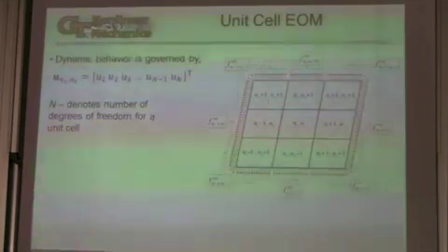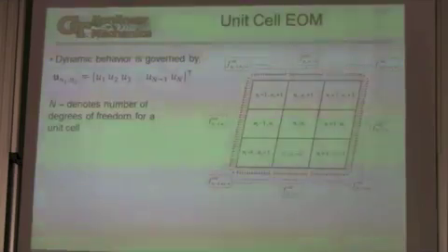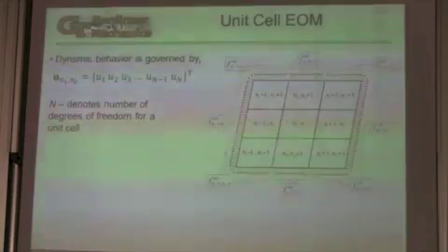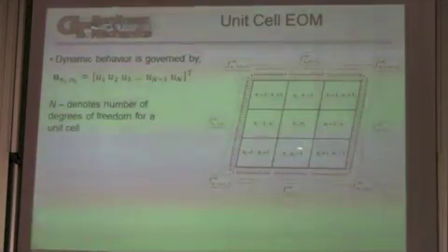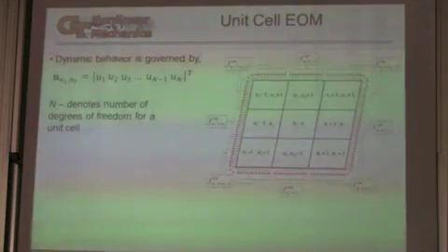Now, the promise with this periodicity is we can reduce everything down to a single unit cell. Let's say we're going to work with the center unit cell. And when we work with linear systems, you can do just that, in fact. You don't have to include all the neighbor cells. Here, we have to include them because we have nonlinear interactions, and therefore the classic Bloch theorem doesn't hold in the nonlinear setting. So we're forced to work with the cells surrounding our reference unit cell. We're then forced to do something asymptotically so we can get rid of all these other cells, at least at the zeroth order, and then find our correction.